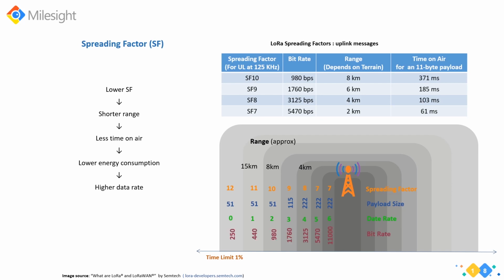And I think understanding this feature of LoRa is quite sufficient for us to understand the bit rate and, later, the receiver sensitivity. So here we can simply remember that a lower spreading factor means a shorter, smaller range and less time on air, with lower energy consumption, so you can extend your battery life, of course. And you can send at a higher data rate, so the frequency to send data is much higher, so you can send a little bit more data maybe.